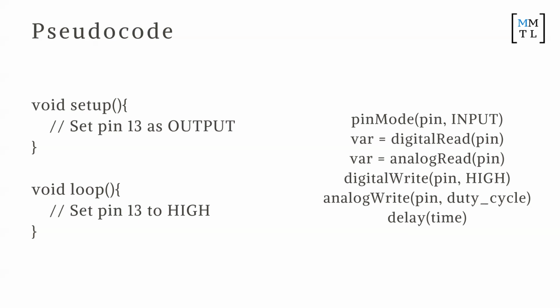So how do you set the pin 13 as output? Which of these functions? Alright, so what's it? Yep, pinMode, 13, OUTPUT. Run the code, yeah.